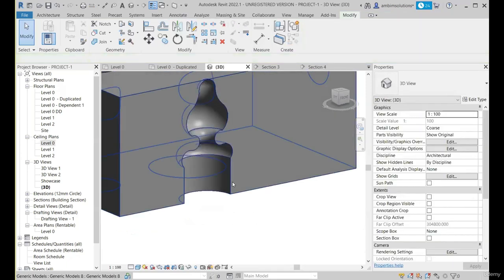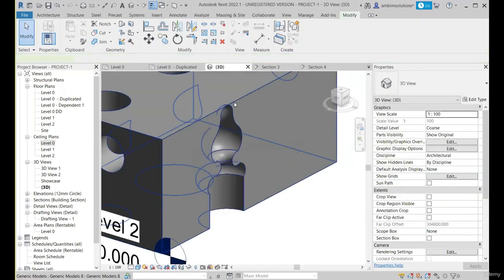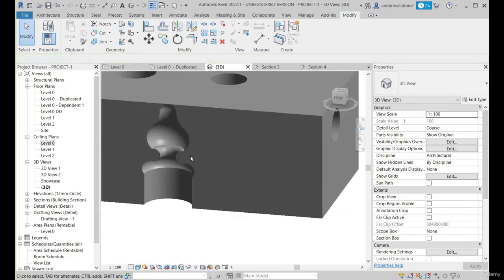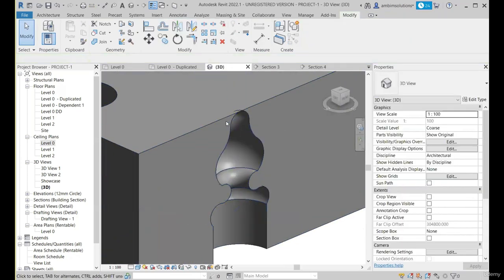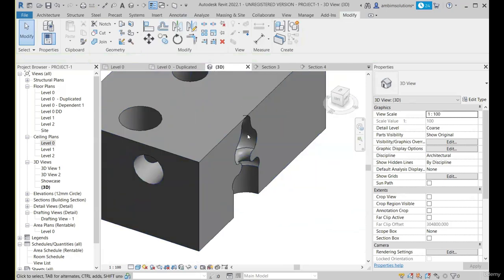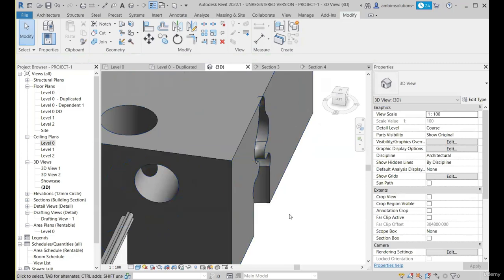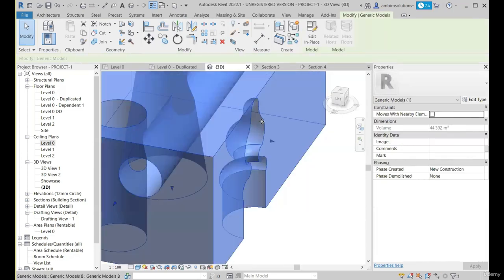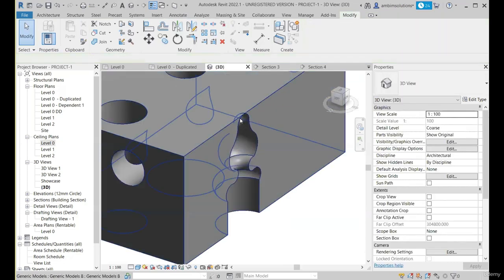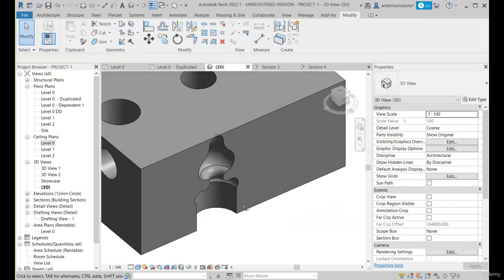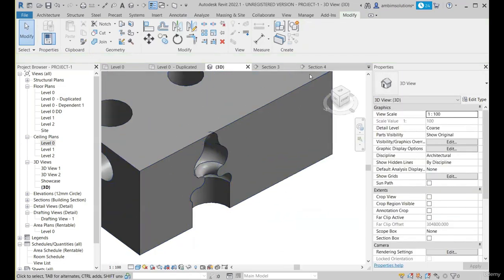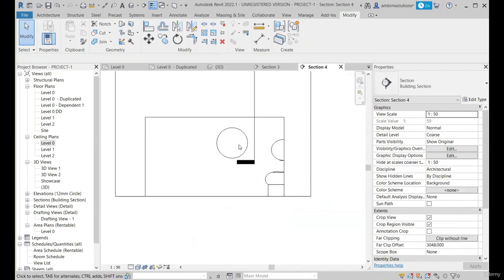Because the solid geometry was present on this side only, the cuts or the holes created because of the shape we have created using revolve are visible only at the solid surface. The revolve is present truly, the complete 360 degrees, but the void cuts the solid, so only the depressions at the junctions of the solid and the void are visible. In this way, you can have the revolve void used.